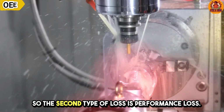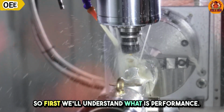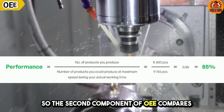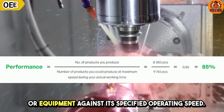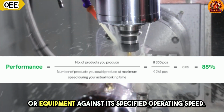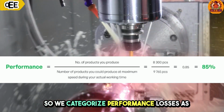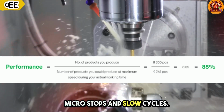So the second type of loss is performance loss. First we'll understand what performance is. The second component of OEE compares the actual running speed of the plant or equipment against its specified operating speed. So we categorize performance losses as micro stops and slow cycles.